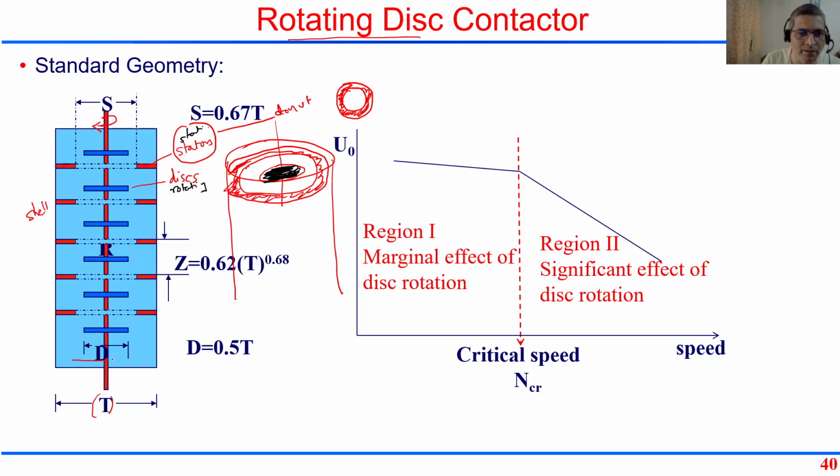The dispersed phase that we are supplying is, let's say, supplied through this distributor. The droplets are generated. Each of these compartments behaves like a mixer where power is put in by the rotation of the disc. That creates the breakage of drops here. It causes the mixing of the drops, breakage as well as mixing. Mass transfer occurs here. The drops go to the next stage through this gap. Are you able to visualize? Drops are coming from bottom to the top through the gap in this washer or donut, if you like. Then it comes into contact with this disc again. Again here it gets mixed up.